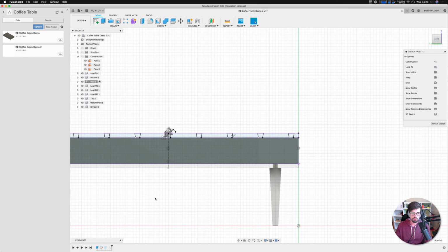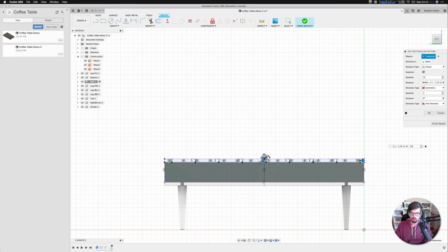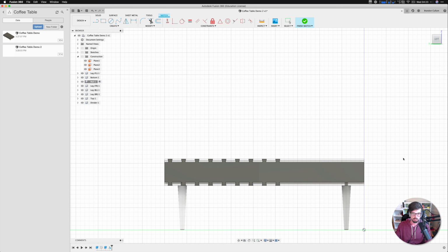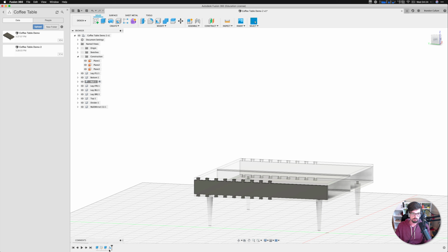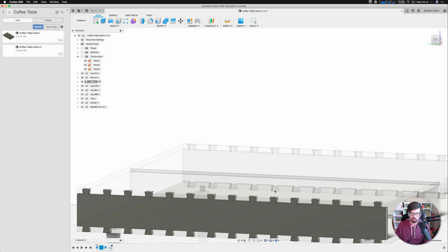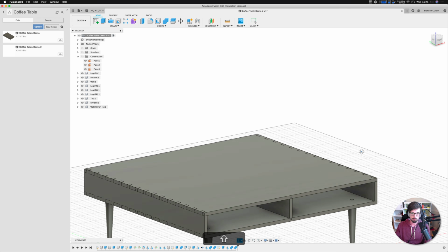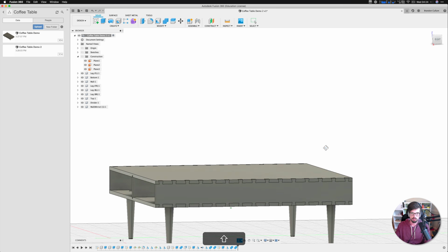You edit the sketch, you jump in here, and then you can increase this number to 15 maybe. Then you finish it. So then what you would have to do is actually go into this and make sure these are selected, since these are new bodies. That's going to join, take it back here, and then you can see that goes to everything else.